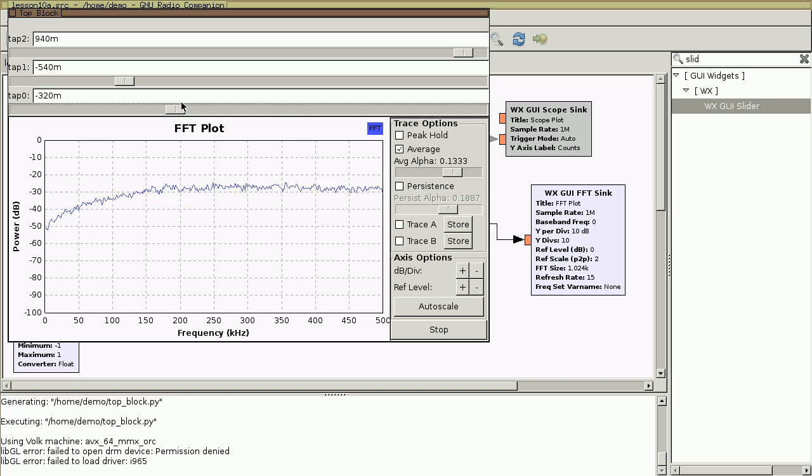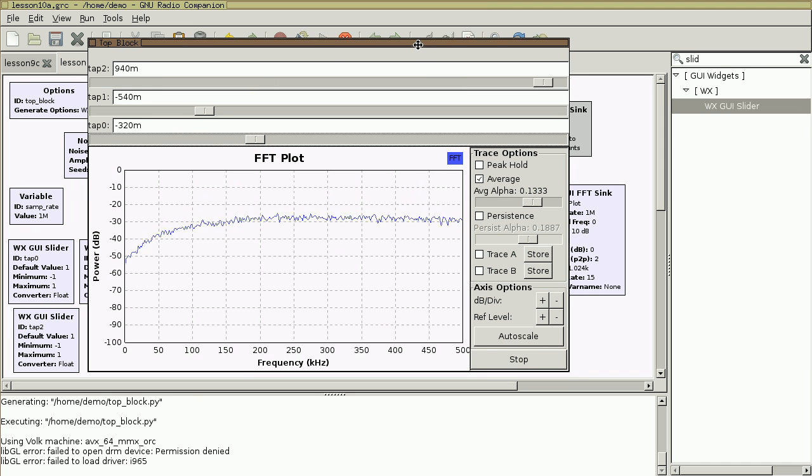Look at that. I can even create a high pass filter. Just by fiddling with these sliders randomly, I found that I can create a high pass filter instead of a low pass filter. And all we're doing is making a moving average that is weighted. And I'm changing the weighting. And those values, those coefficients of the weighting, I call taps.